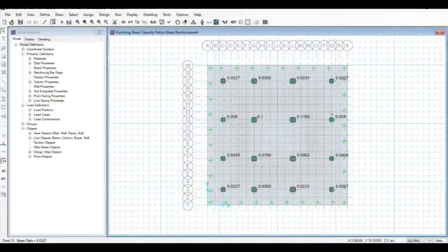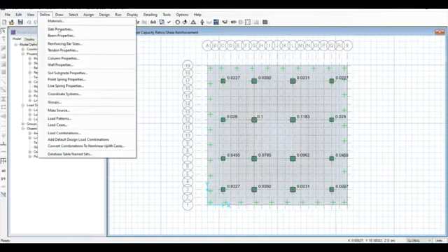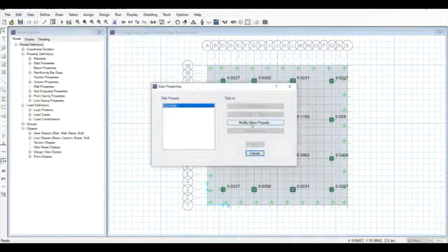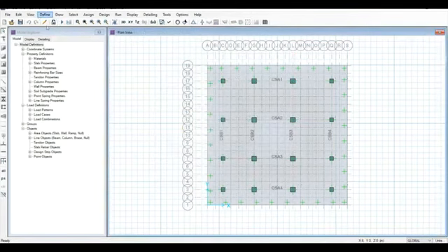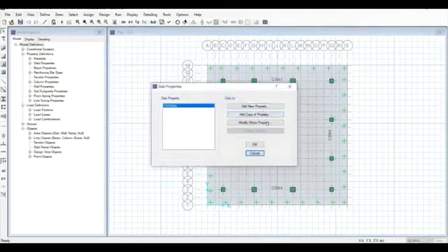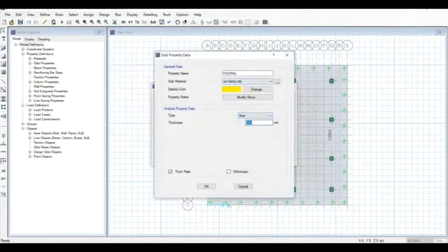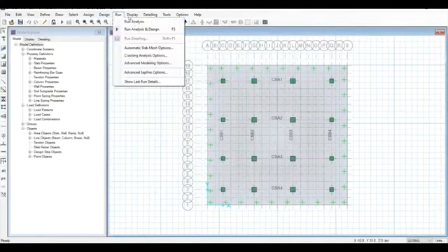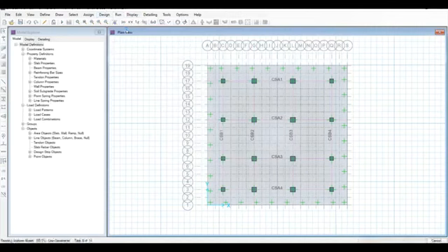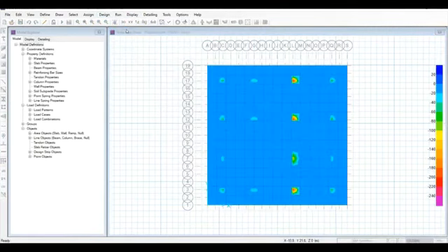If any values are different, then we need to go for define and change the slab properties of footing. Modify. As we are in locked position, we need to unlock it first. Define slab properties, footing, modify our slab footing and change the values from 200 to 500, and then click OK. Click OK, and then you can go for analysis again. As we have already got safe values, there is no need to do this. Our values are all the same.